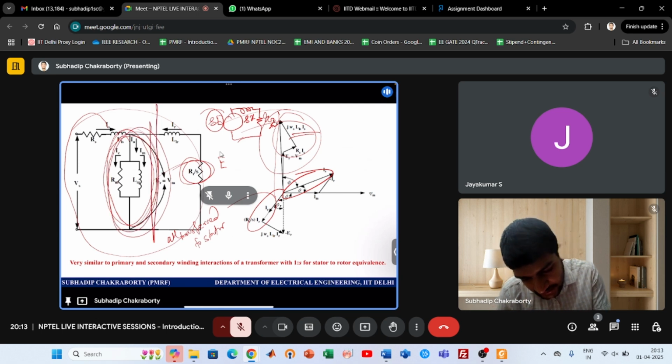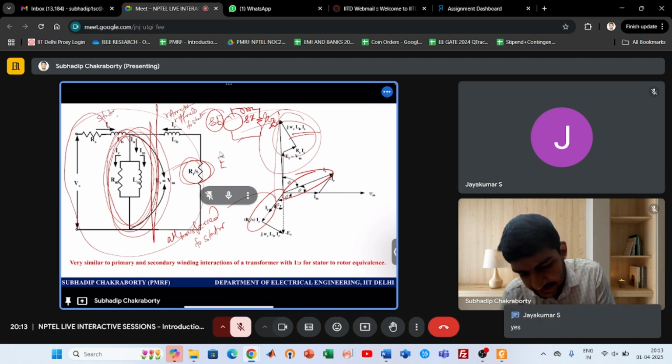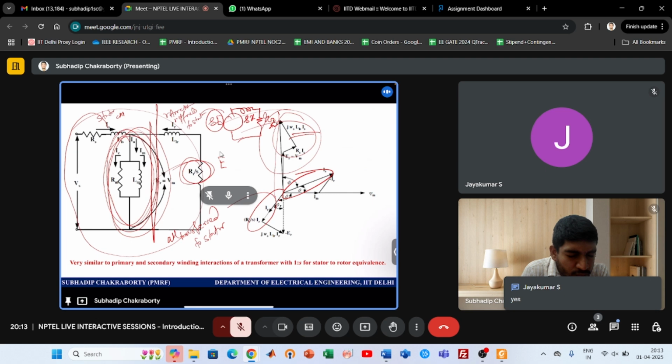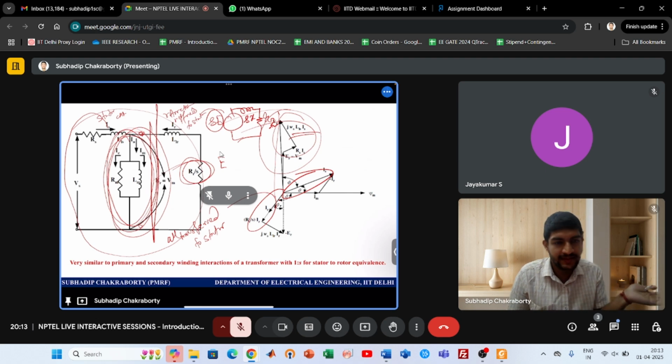So after this is the rotor circuit, referred to stator, and this much is the stator circuit. To couple the two, you need a common voltage by network theory. And how can we do it? We can just shift the secondary voltage, which is S times E, away. So 1 by S, and then operating frequency also changes. Please note operating frequency is changing. That's why 1 by S times only.